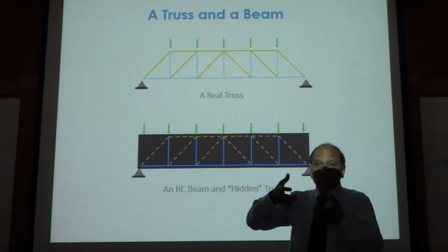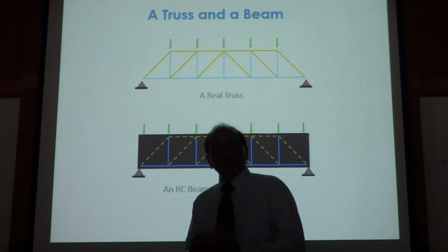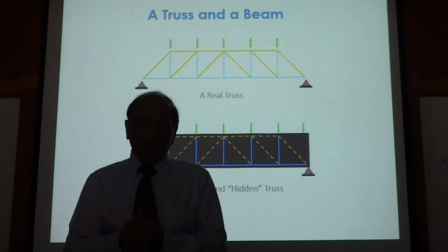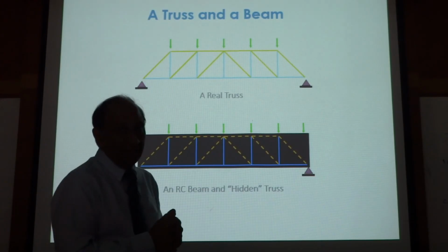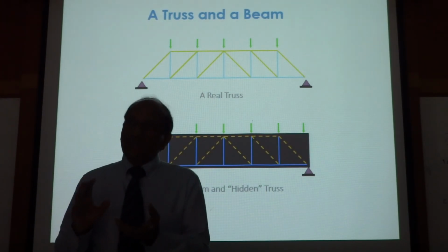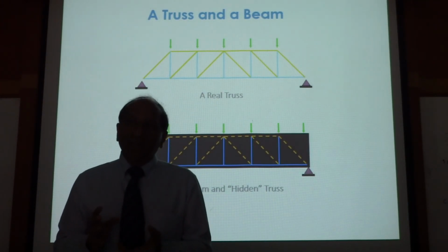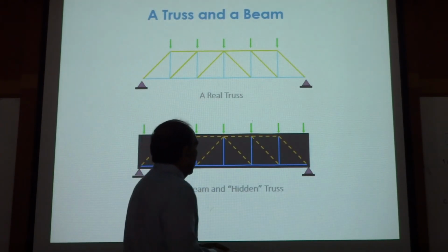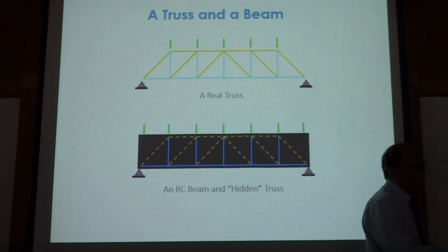First, you use the bending theory, and now we are going to use the truss analogy, or strut and tie approach, because this is not a real truss. There is still concrete in that, right? But we are saying that it behaves the same way as if it was a truss. And now we will go into more detail and see when and how we can use this concept.